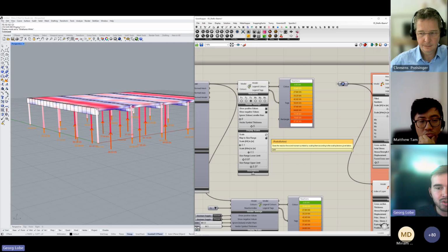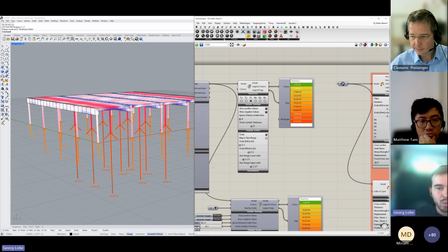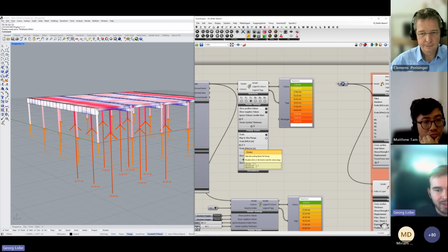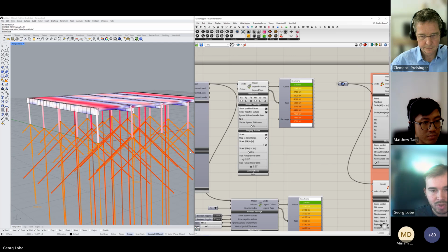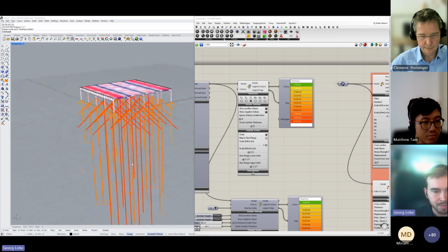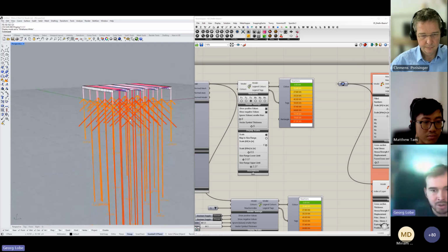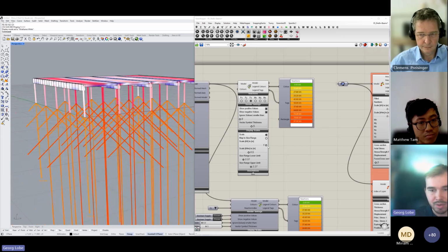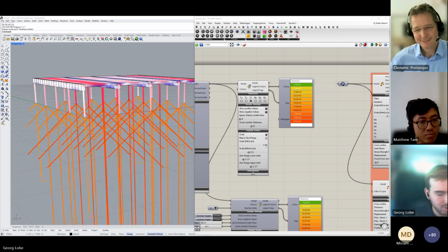Also, you can change to absolute scaling, where you have the upper two sliders available, which just scales the kilonewton value to the meter scale. So if I change this to 1 kilonewton would be 1 meter, the largest arrow is 87 meters long, but we don't want that, so I change it back.